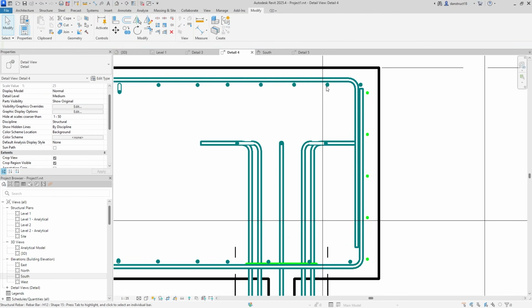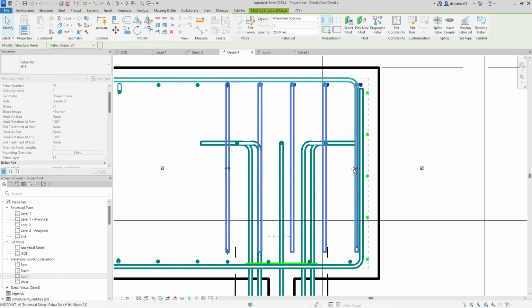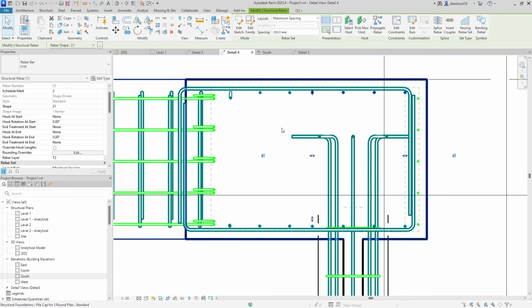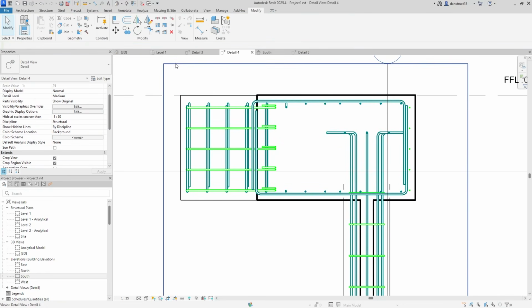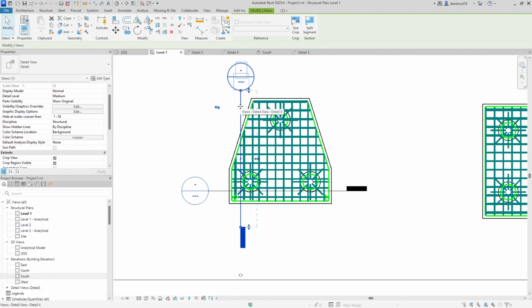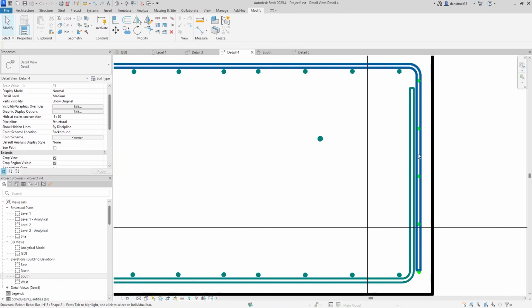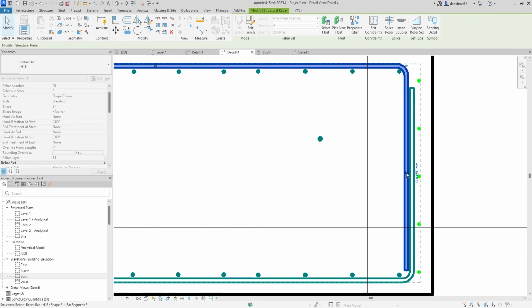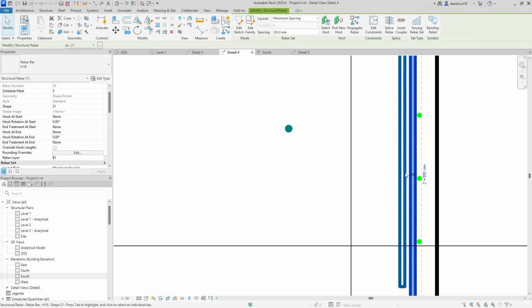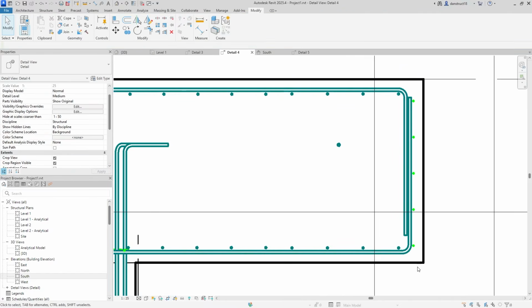Likewise, I'll select this bar. There we go. And I'll nudge it to this point here. Great, good. So we'll do the same thing in the other directions. Just select this, and I don't need to copy. I can just drag it to this direction like this, then double click to open, and make sure that I fix that in all the directions. So select this, then drag this one here to this point, set this here to 800, press enter. Select this, change this here to 850, press enter, and maybe just nudge this one to the side a bit. There we go. Anything for that lovely detail.